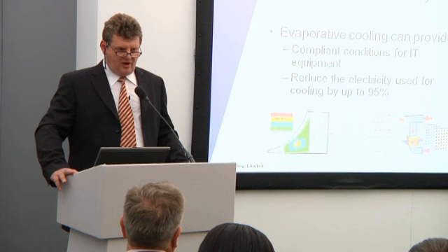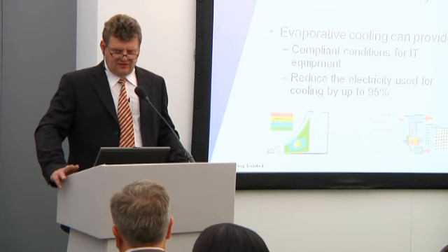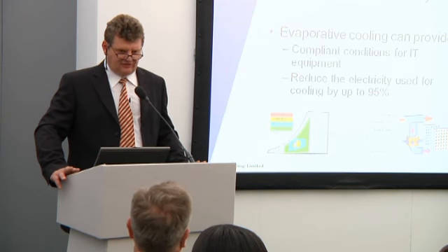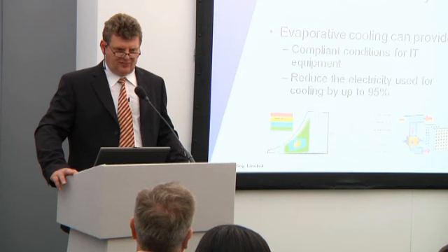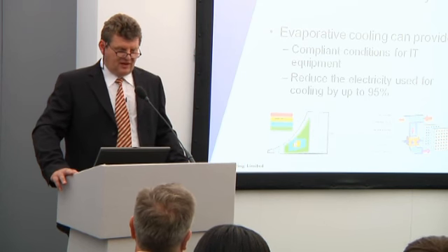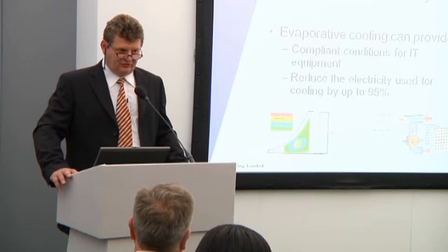If you embrace that widening of those operating standards, then you can implement a ventilation scheme based on these principles and reduce the energy bill of your cooling by over 90%. Now, in most cases, that means that you can reduce the energy usage of your data center by a half, with a capital investment which could pay for itself in under a year.